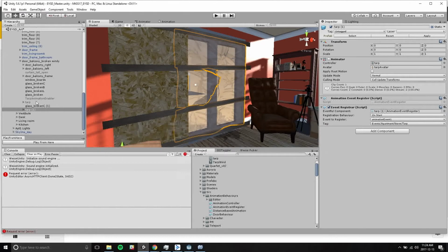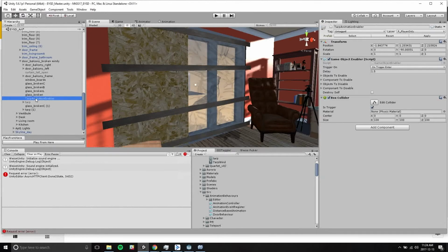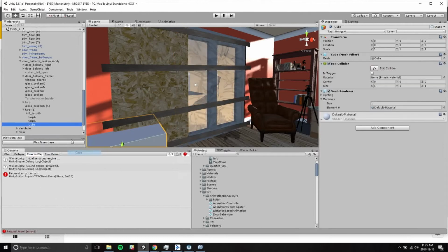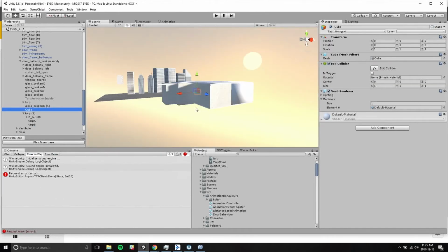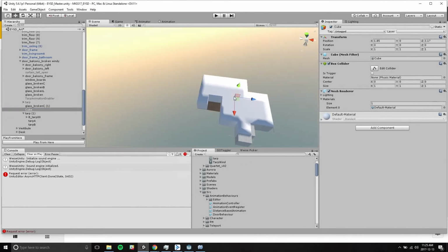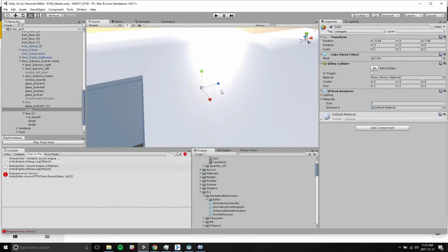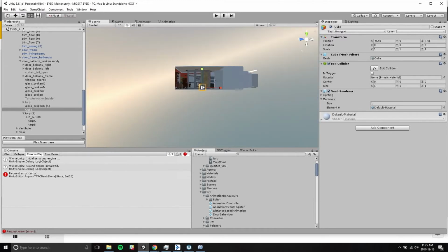The last thing I need to synchronize the animation properly is to disable the animator for the start of it. I can just create a new one here. So we create a slight delay in the animation because this animation loop starts on the scene load, and what we found is that sometimes it starts just a little too fast and the sound bank hasn't completely loaded yet, so we have to wait for the next animation loop for the sound to start triggering. So just by giving it a 1 second delay, we make sure that the sound is playing from the very beginning of the scene.